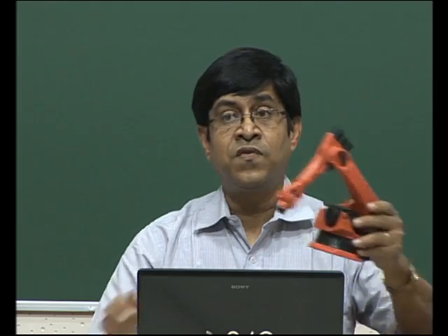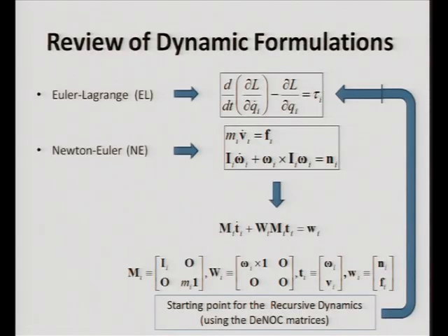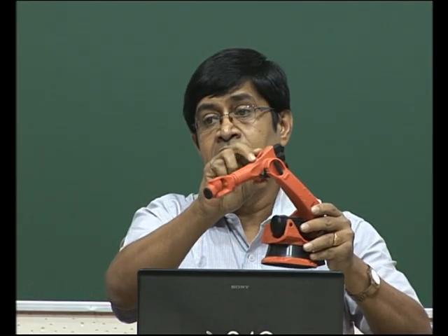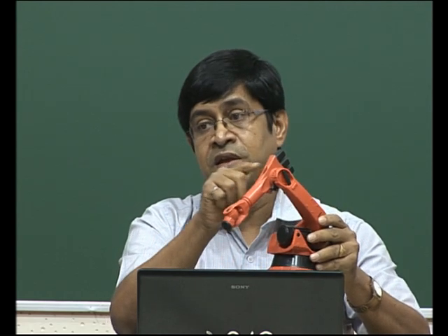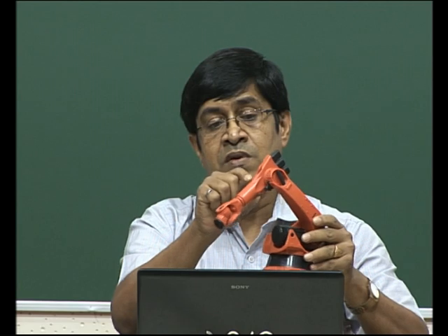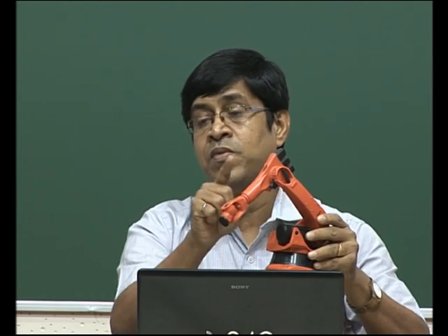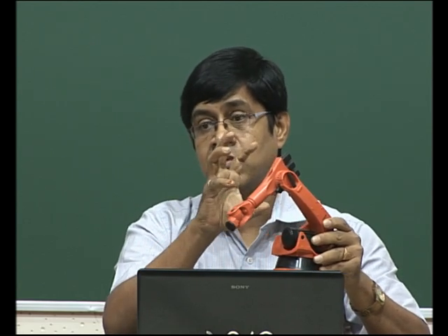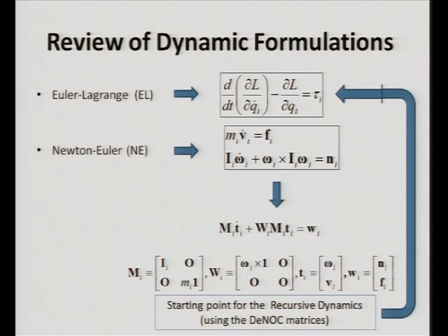So, even in order to find out the joint torque here, you will end up also calculating the reactions coming on the bodies, like this body and that body, but all of them are not required. They are required to keep the links intact. What is required for us is the joint torque, but you have to calculate the others. For inverse dynamics they are not actually required, but we calculate them because of the formulation.